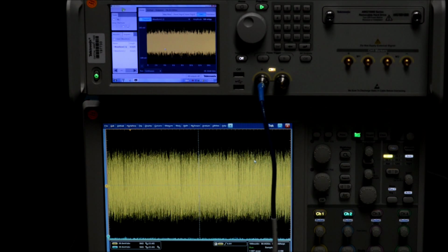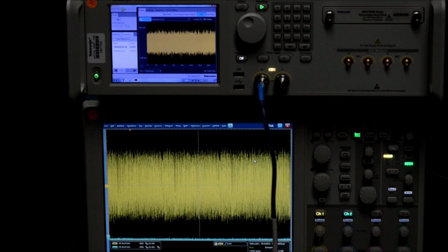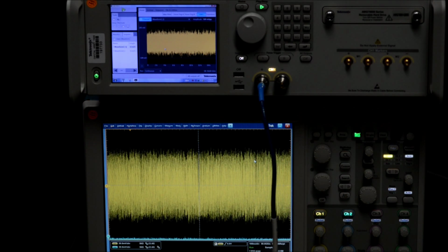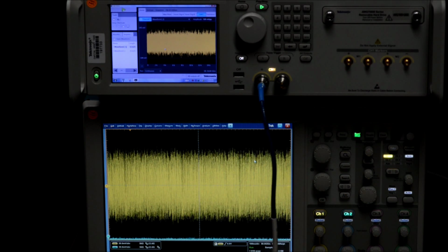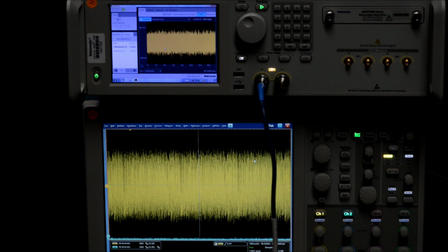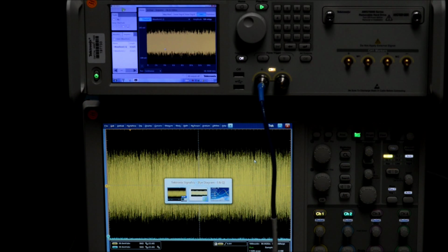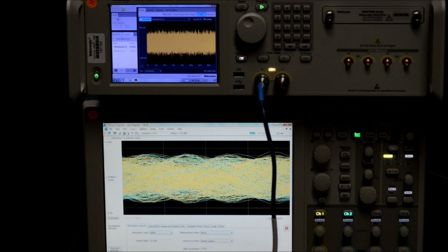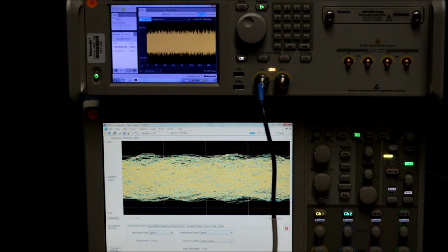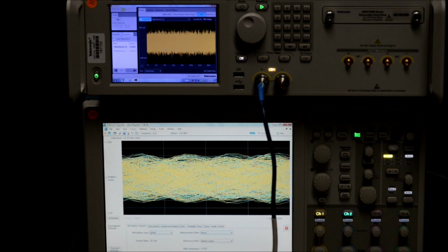When we're doing this IQ type of calibration, we can only do calibration on one channel at a time. So in this case, we're basically showing the Q waveform which was not compensated. So what I want to do is show you in signal view what it looks like, and of course we wouldn't be able to use this waveform too much. So this is an uncompensated waveform directly out of the AWG using the compilation that we created.